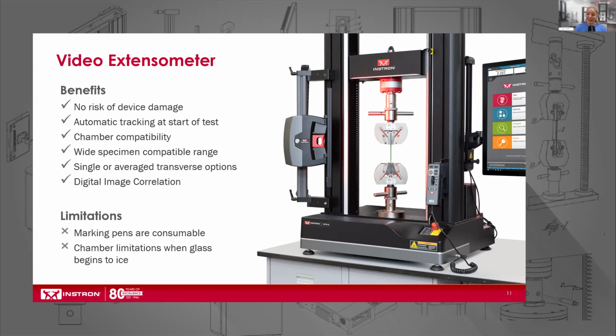Being a video-based platform, there are more flexible options for analyzing those live images that your device is pulling in. You can track axial strain, you can track single point transverse, or you can configure the device to measure and average multiple points in the transverse direction. And this is often our recommendation for sheet metal customers because it can greatly decrease your coefficient of variation when you're trying to determine R value.